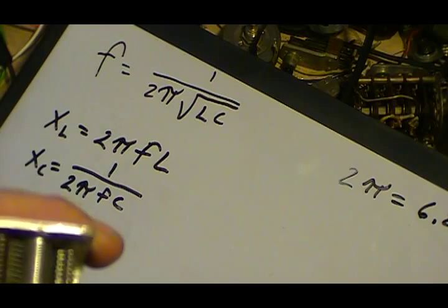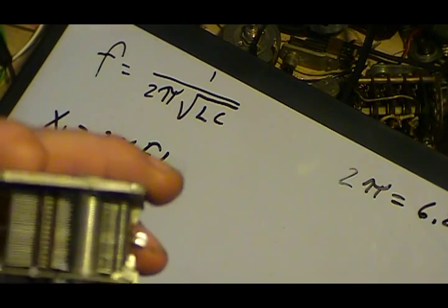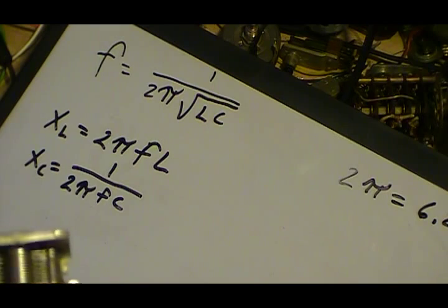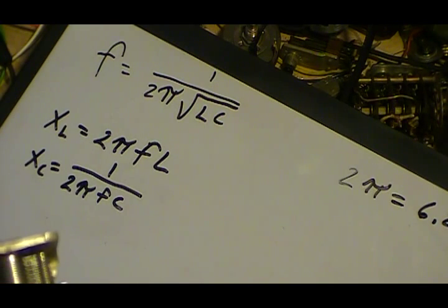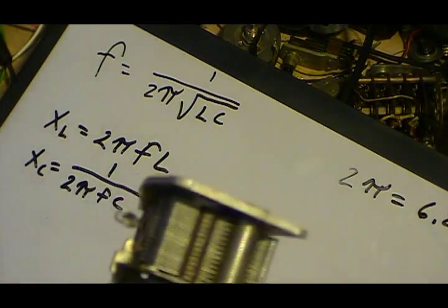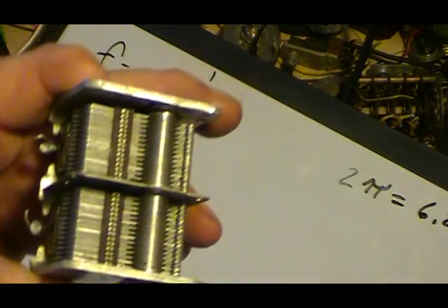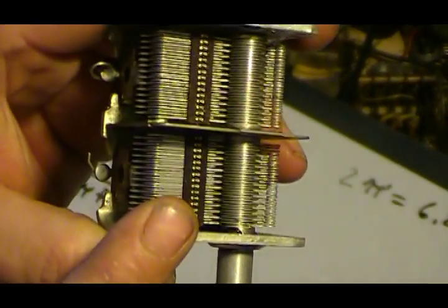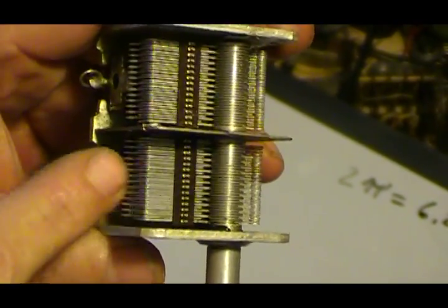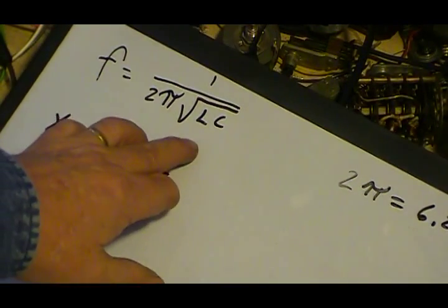So the next time you're ever messing with a radio and your alignment instructions are rather vague, and they just tell you to tune to 550, the low point on the band, then on AM band or whatever band, but the radio is out of the cabinet, you don't have a dial or anything that tells you where that's at, you'll know that that's the low end, that's the lowest frequency. So that's going to be when the tuning condenser is fully meshed, because of this formula.